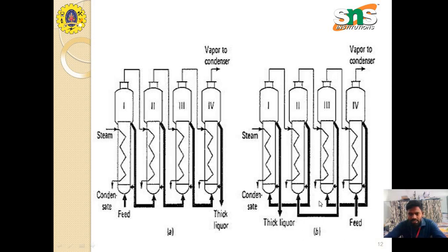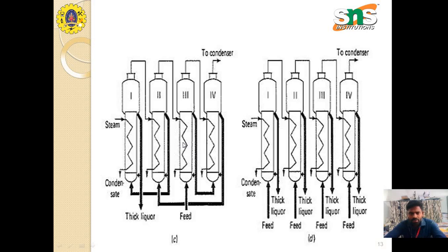in the first container. And then the third one is the mixed feed multiple effect evaporator. See here in the diagram, the steam is supplied in the first container, that is, the first evaporator. Here we have 1, 2, 3, 4, so four containers. It is not restricted to four; you can take five or any number of containers, or evaporators, for the required output. If you want to evaporate a huge volume of feed, then we can add more evaporators for an effective process.